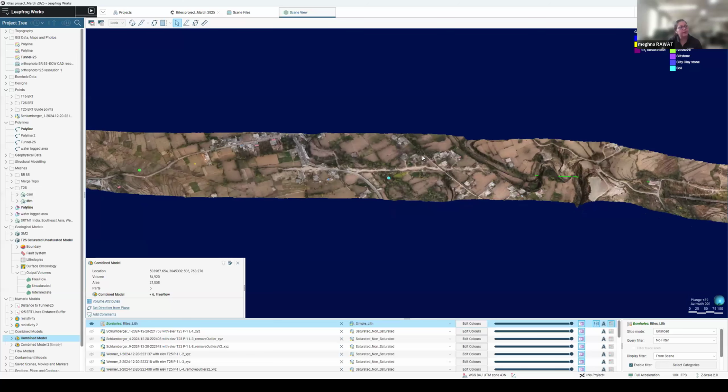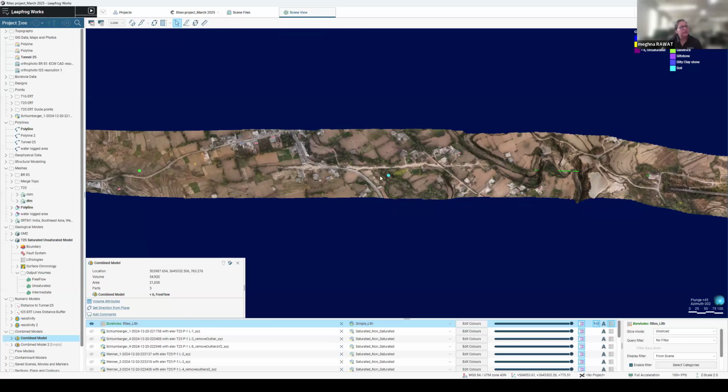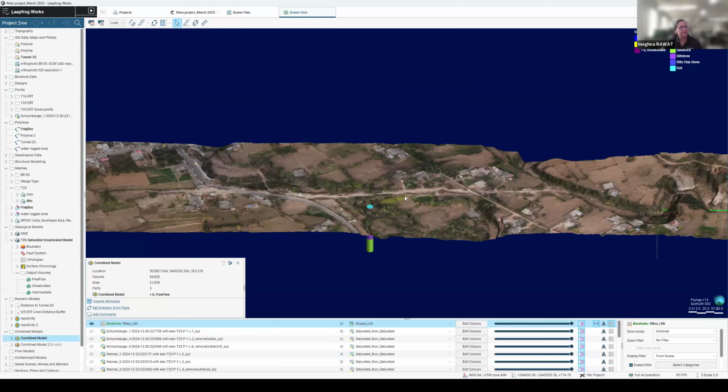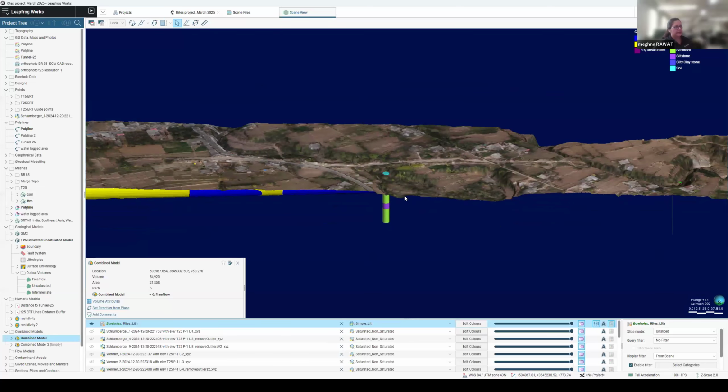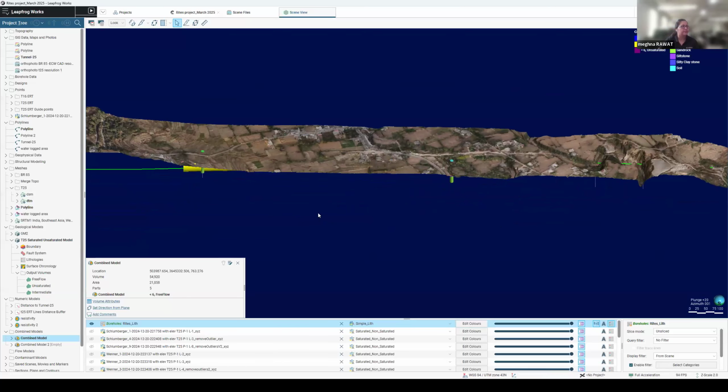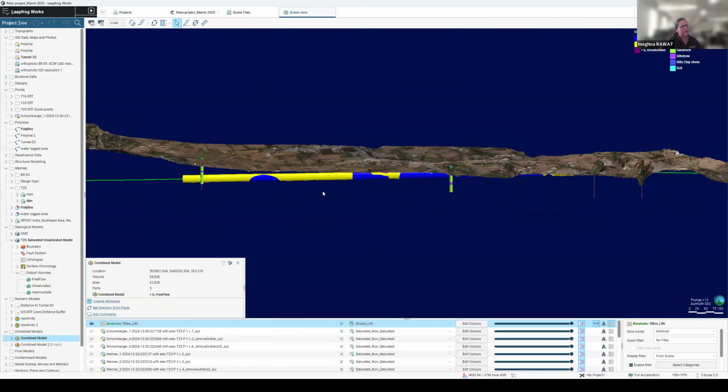For example, here I have this nala flowing. We can drill one more hole here and one more borehole somewhere at these two locations, so that we can understand the depth of the groundwater table and exactly how deep the water level is. In this manner, we can propose our additional investigations.